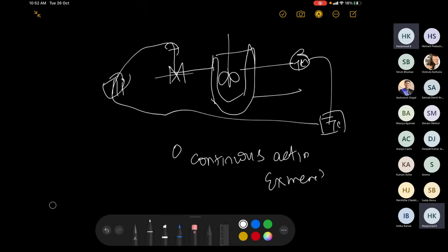What would happen then? If there is a small temperature change, you wanted to make 80 degrees centigrade, and it has become 80.1. Your controller is now saying, oh my goodness, everything has collapsed. Do something. Okay, make the valve fully open so that the temperature is down. Suddenly it becomes 79.9.